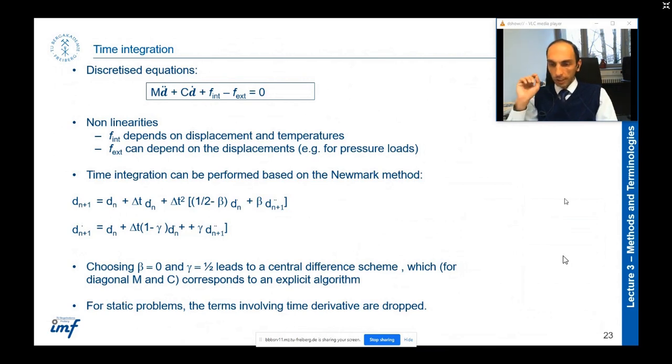When you need the strain rate, it's dependent on the time, right? Because the definition is d epsilon dt. So beside discretizing the geometry and breaking it down into small elements, you should discretize the time.